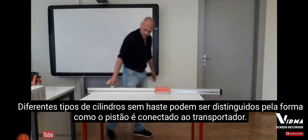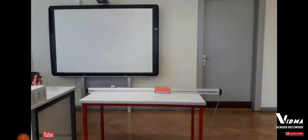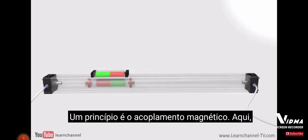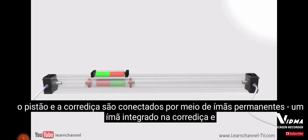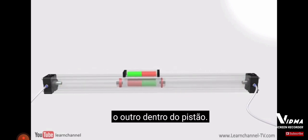Different types of rodless cylinders can be distinguished by the way the piston is connected to the carrier. One principle is the magnetic coupling. Here, the piston and slide are connected together by using permanent magnets. One magnet is integrated within the slide, the other one within the piston.